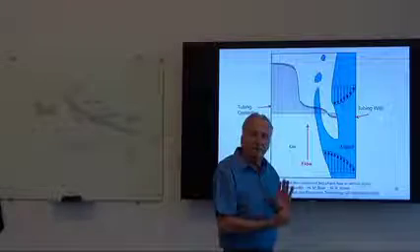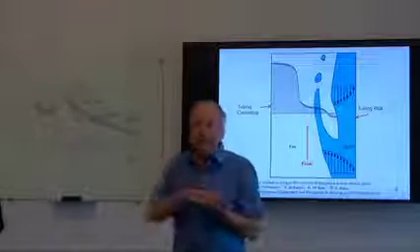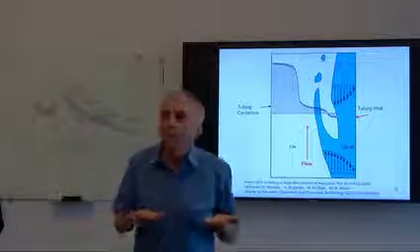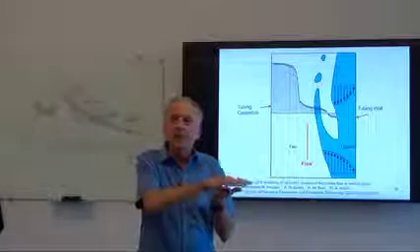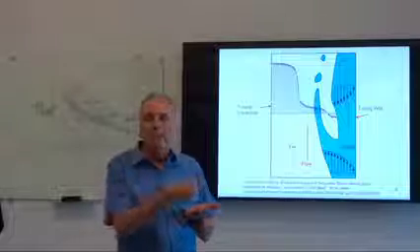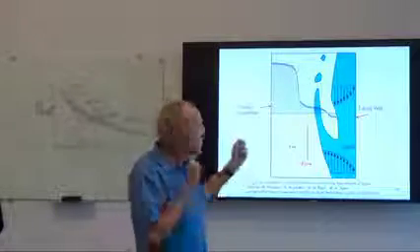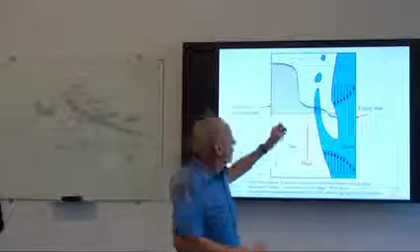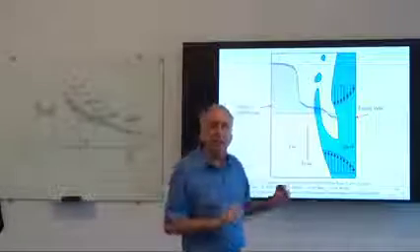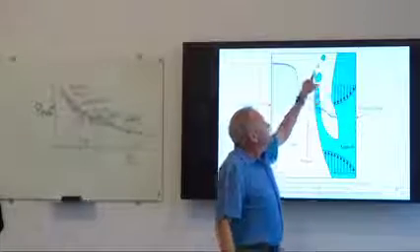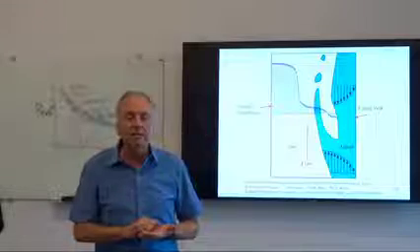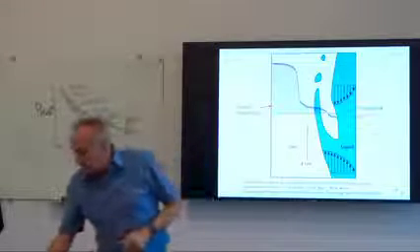We get kind of waves, just like you would across any liquid surface. If we were to blow wind across a lake or a pond, we would get some wave action. And if we blow harder, we get perhaps some white caps or some frothy surface. And that frothy surface might shed some liquid. We would call it spray if we were standing there by that body of water, but inside we get the droplets getting created and re-entrained into the gas flow.